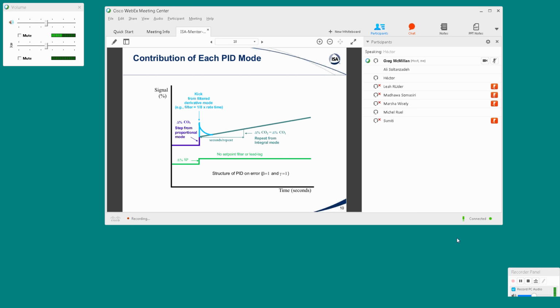Yes, great. When you were talking about the runaway processes, and we're also mentioning that it will probably not be desired to have the loop make step changes where the control loop is not in control, is the closed loop tuning method the recommended way of tuning? Is it reliable? It is more difficult, and I think for runaway processes and for some of those furnaces I mentioned that could ramp off scale, you have no alternative, and there are several different closed loop methods. Actually, the relay oscillation method, even though it's very unpopular, if you choose the right step size, will keep crossing the set point and come up with the tuning settings.